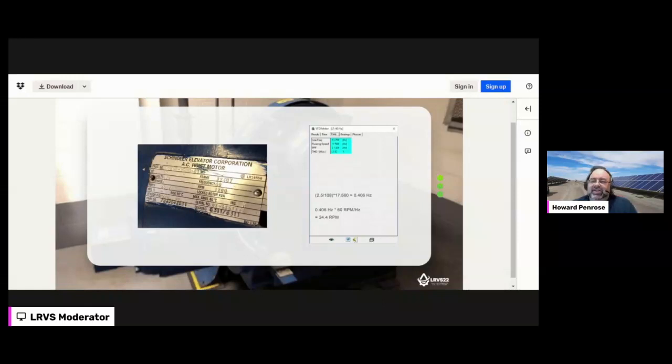So what happens if I see a bearing defect in one of those? Well, I just don't know which one it is. The good news is it's a 25 horsepower motor, so chances are if I have a bad bearing, the whole motor's coming off and you're replacing both bearings anyways. But when I get into larger machines, say a wind turbine, where I have a 6330M, 50 odd pound bearing, and access to either side takes half a day, that becomes more important.